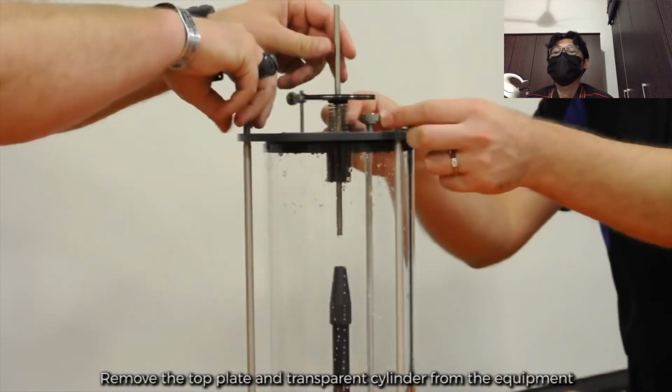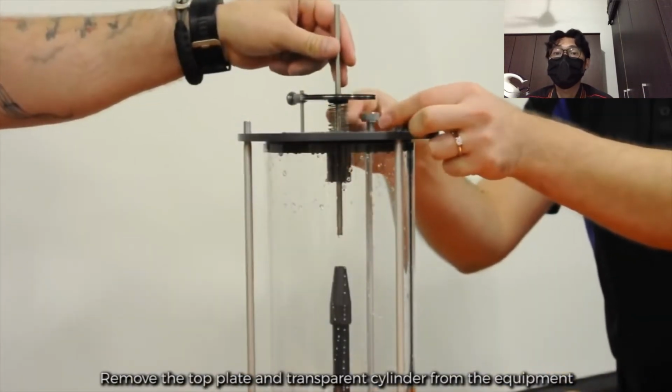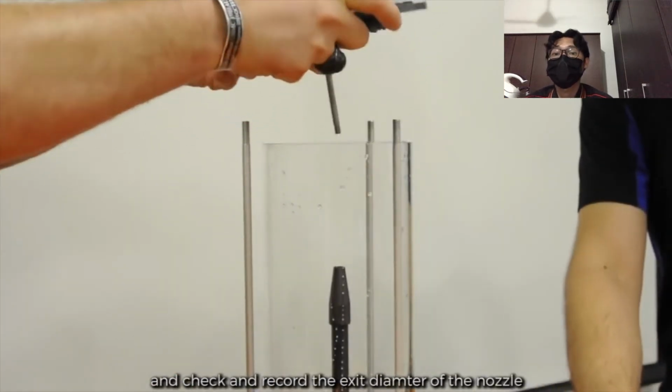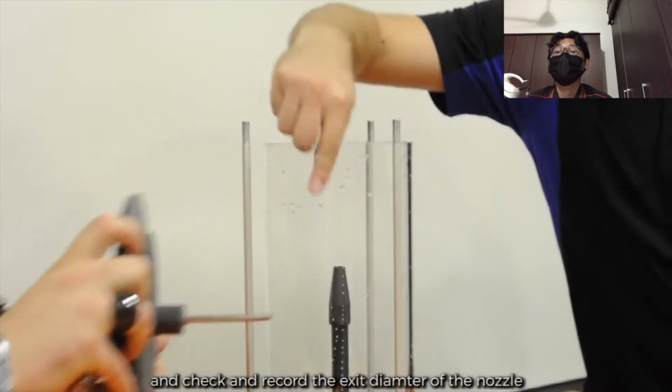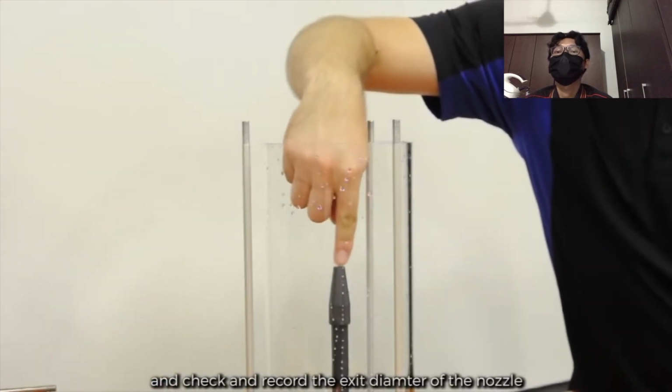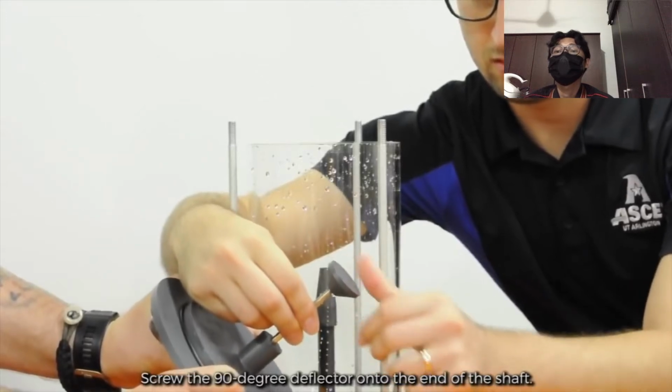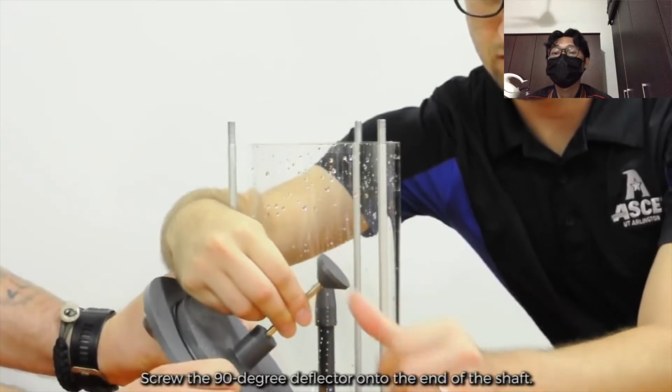Remove the top plate and transparent cylinder from the equipment, and check and record the exit diameter of the nozzle. Screw the 90-degree deflector onto the end of the shaft.